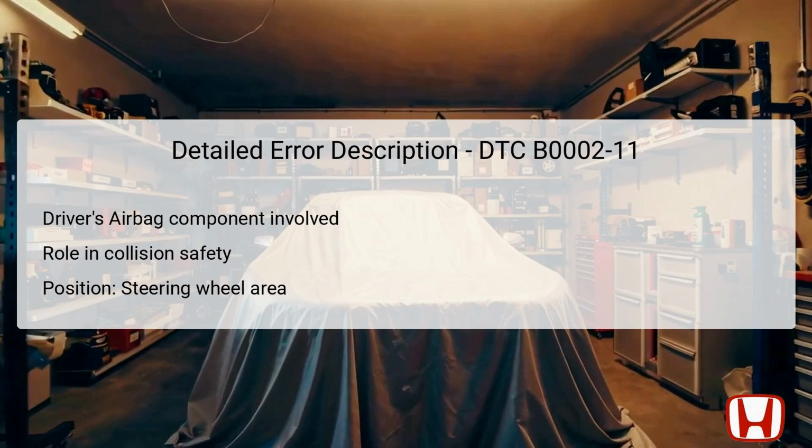Additionally, the cable reel connected to the steering wheel allows for the completion of electrical circuits while enabling the wheel's rotation. The SRS unit monitors these connections, and if it identifies a short circuit or failure in this line, it will store the DTC B0002-11 as a fault code.